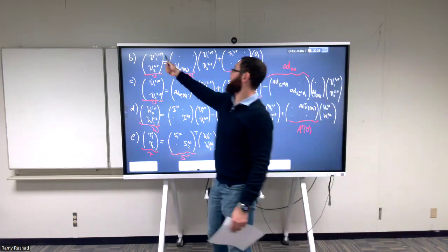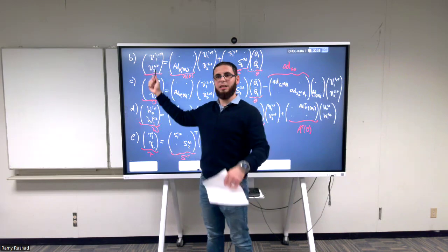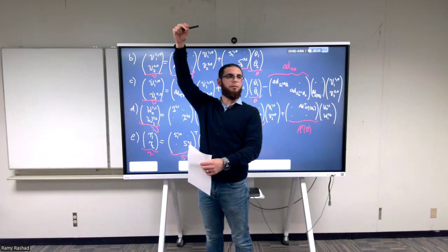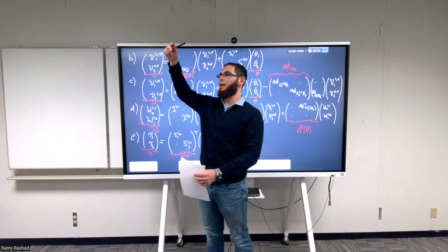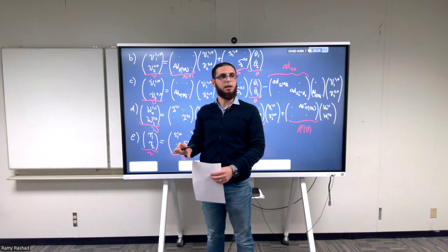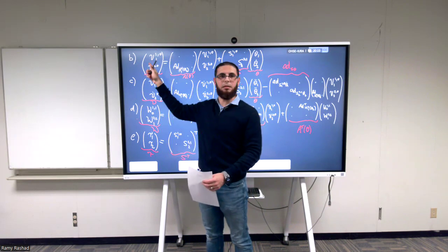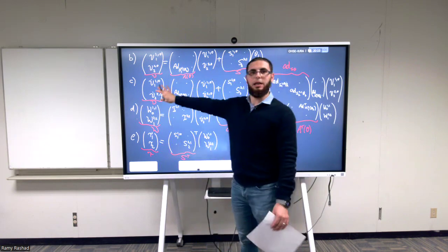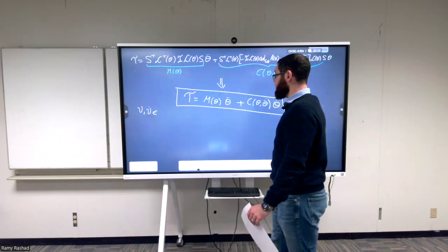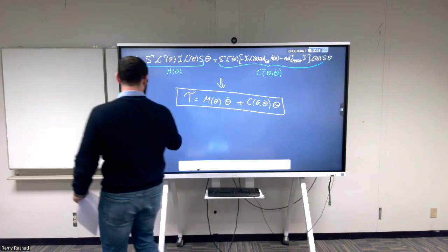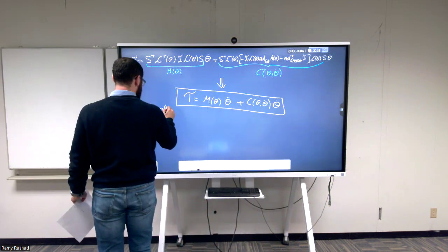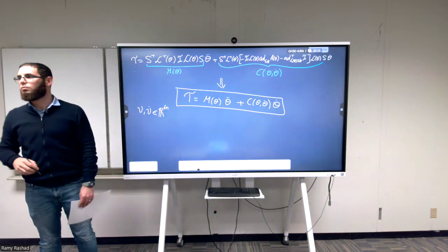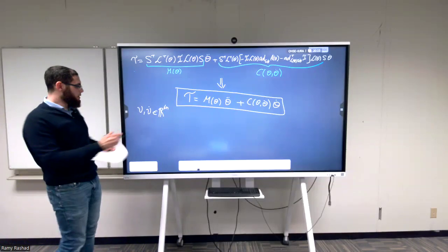In this example, I have 6 by 1 and below it another 6 by 1, which means it's 12 by 1. If I have an n-link manipulator, then I have 6n by 1. The V dot is the same. So in general, these two live in 6n by 1.